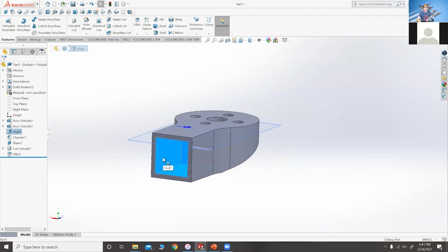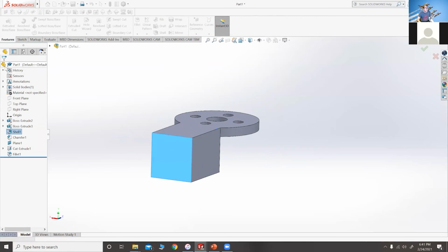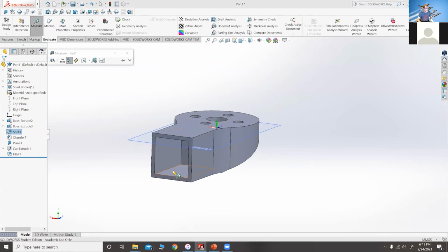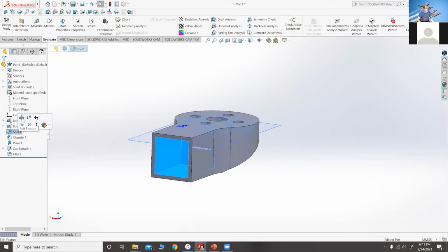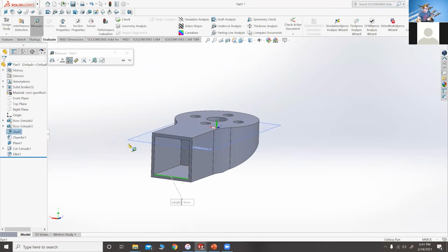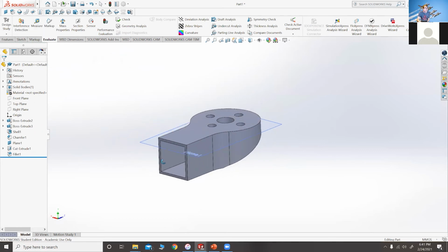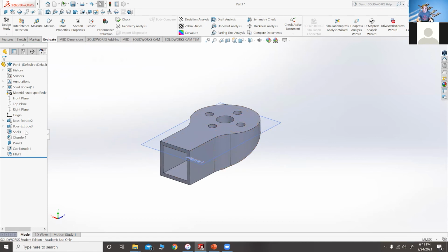the tolerancing that I talked about earlier for the 12 millimeter spar, the spar is actually about 13 millimeters. So we can go and edit the shell command later, and we can say we want our shell thickness to be 1.25. It's 12.5, it should have been 1, but do your math correctly and you can get a 13 millimeter hole here now. So you can change things from earlier on, and I'm going to undo that.